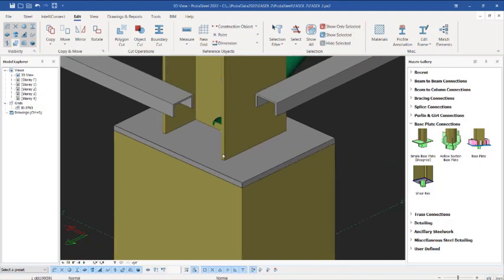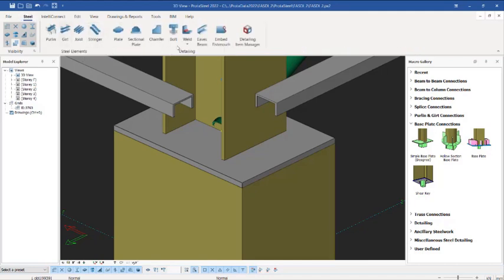Okay, this time around we want to be adding holes on this, followed by the anchor bolts, so that we can actually bolt this successfully. So for us to do that, we go to the steel sections. In these steel sections, you see bolt here, this one. Click on it once. Once you click on it, you select the plate that you want to place the bolt on, after which you right click and then you pick the first point right there, come over here and put the second point.